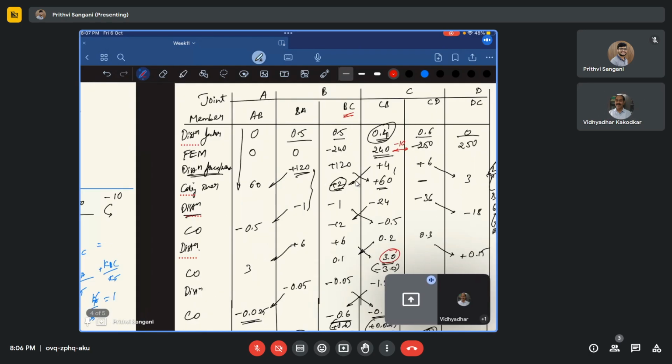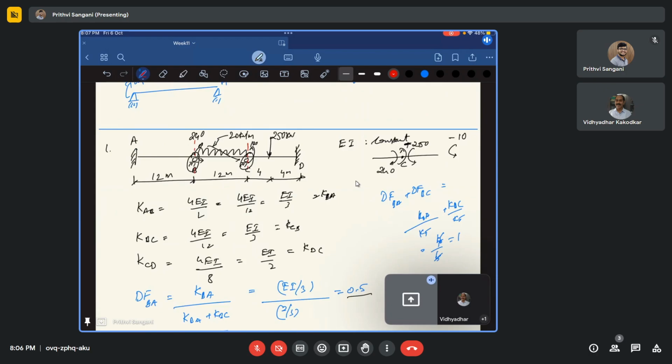Yes, that's what. So initially, in this concept, we assume all the supports are fixed, and then we lock and unlock, lock and unlock, lock and unlock, until the point where, at point C, it is actually a roller support, right? So it's a continuous support. So we do this locking and unlocking until we get MCB plus MCD equal to 0. That means there is no net moment.